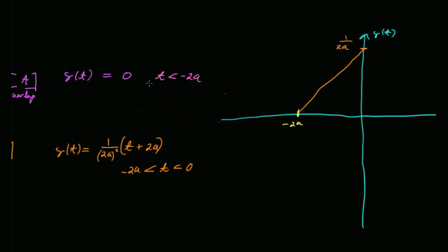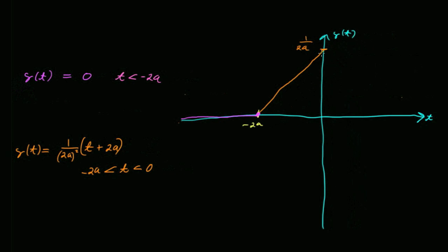So in other words, what the convolution predicts for this function at minus 2a and what it predicts for the previous function at minus 2a give you the same value. By the same token, when I do my next integral for this section, you better be sure that convolution integral will also predict 1 over 2a at t equals 0. Is there always continuity in convolution? Again, as long as you're not convolving impulses, yes. Once you start convolving impulses, it gets a little trickier, but not by so much.